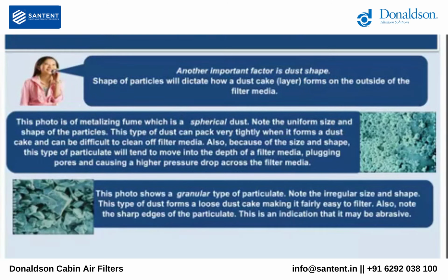This photo shows a granular type of particulate. Note the irregular size and shape. This type of dust forms a loose dust cake, making it fairly easy to filter. Also, note the sharp edges of the particulate. This is an indication that it may be abrasive.